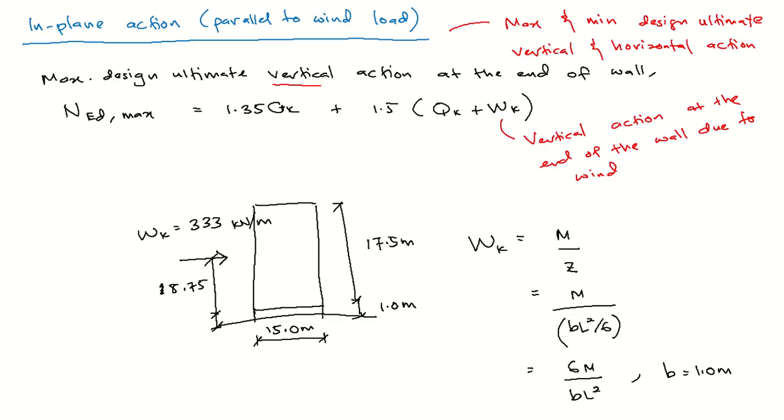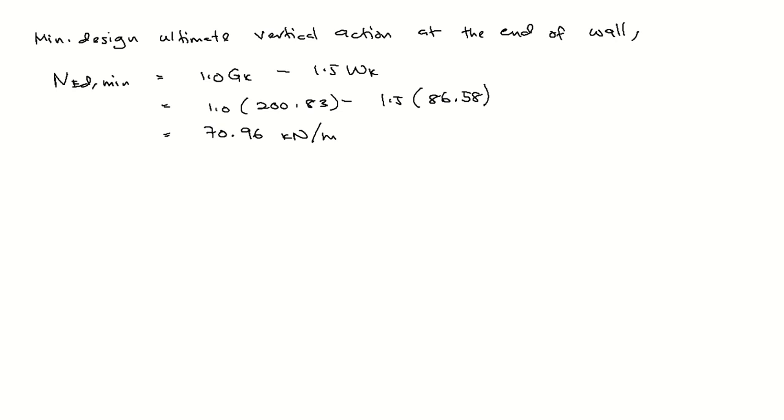Okay, we have the NED max, NED min for vertical action. Now for the horizontal action. Okay, for horizontal action is where we are going to use it for shear design later. Okay, so for maximum design ultimate horizontal shear, okay, VED, horizontal will refer to VED for the shear wall.